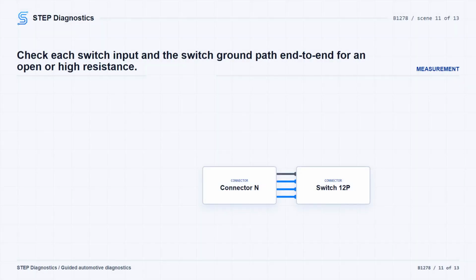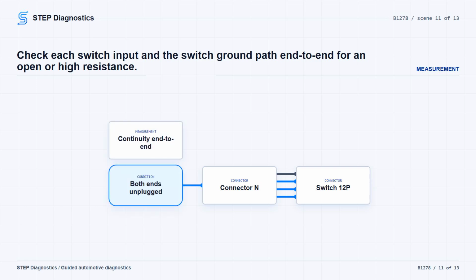For the open wire check, keep the ignition at lock 0 or OFF mode with under-dash fuse/relay box connector N20P disconnected and the combination light switch 12P connector disconnected. Check continuity between under-dash fuse/relay box connector N no. 18 P and K and combination light switch connector no. 1 P and K. Check connector N no. 19 YL to switch connector no. 7 YL.